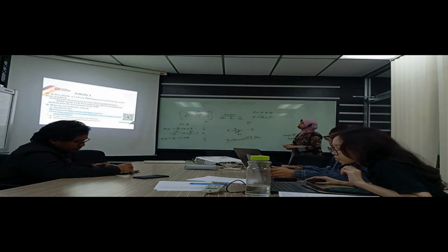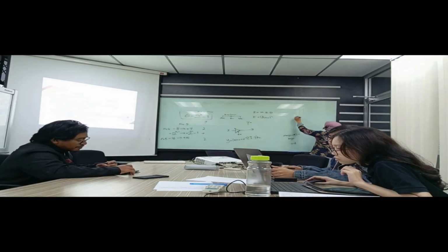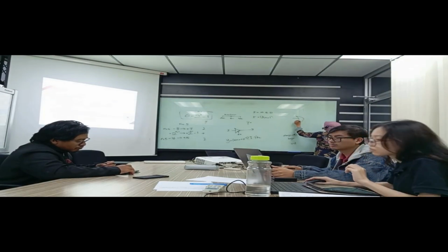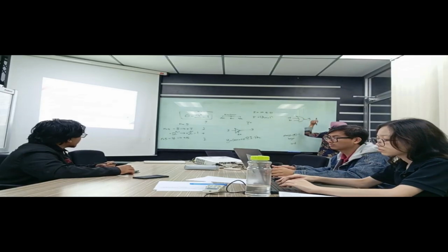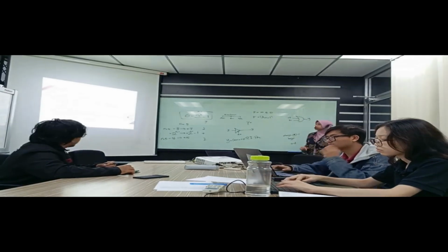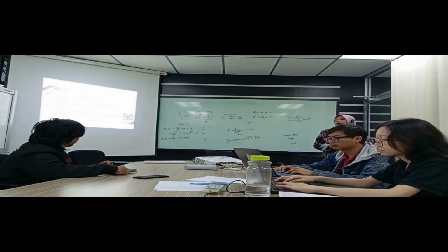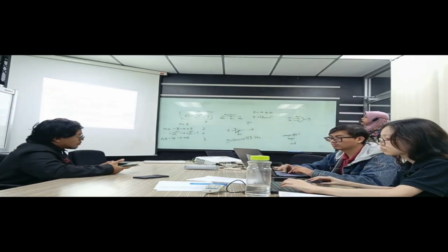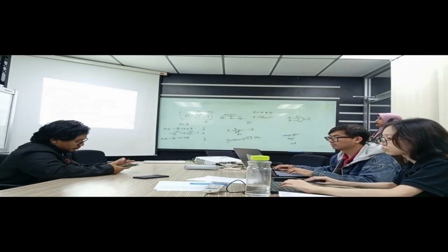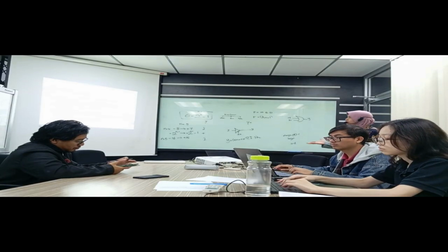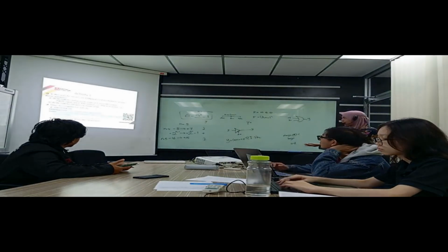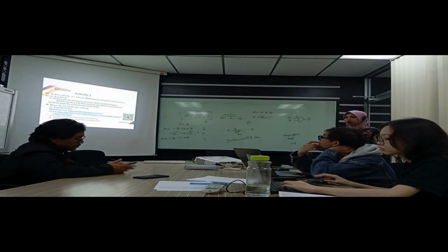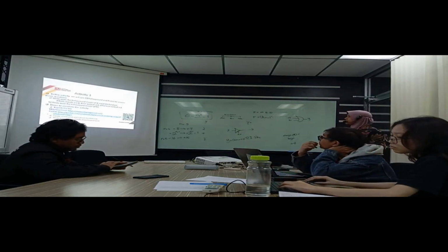So let's say this is the diagram. Your inputs are A, B, and the output is Y. You have to write this in code using behavioral modeling. The statement is if both inputs are 0, then the output is 0. Otherwise, 1. That is the truth table for the OR gate.